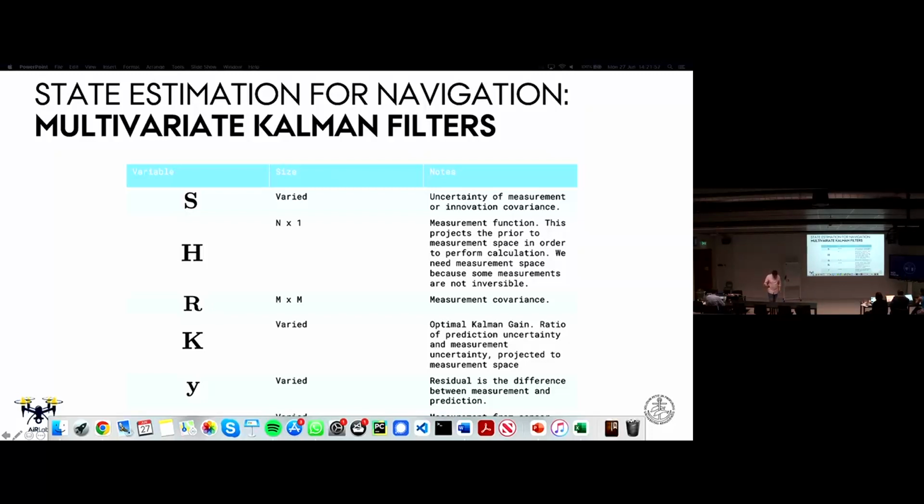So if we know the position and we know the measurement, then we can project that measurement into the state space, and from the state space we can calculate how uncertain we are. This is basically the error term of how uncertain we are given some measurement. And the last thing that you can't see there is Z. Z is basically the vector space of your measurements. If you have 3 sensors, you would encode them into this vector space.